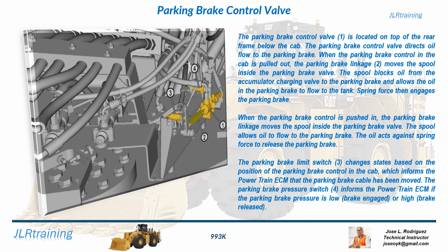Spring force then engages the parking brake. When the parking brake control is pushed in, the parking brake linkage moves the spool inside the parking brake valve. The spool allows oil to flow to the parking brake. The oil acts against spring force to release the parking brake.